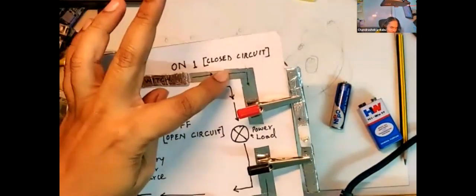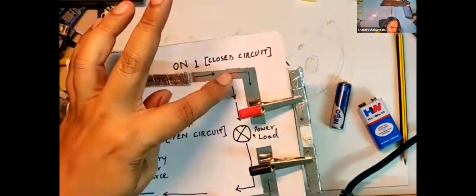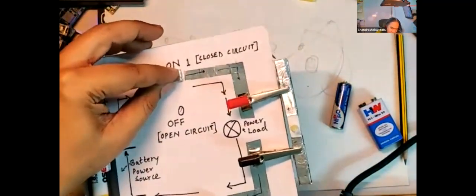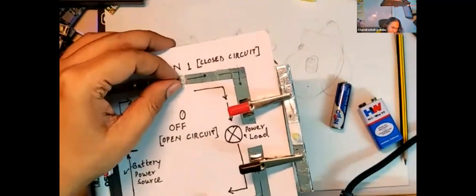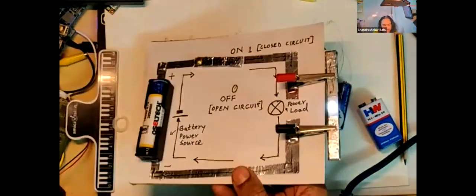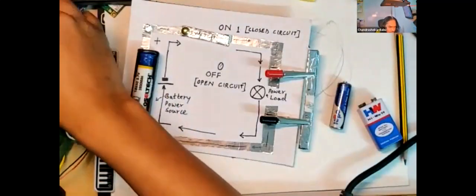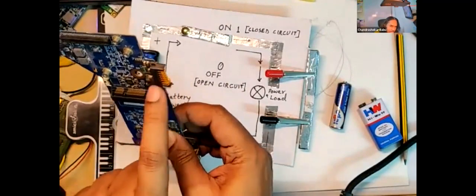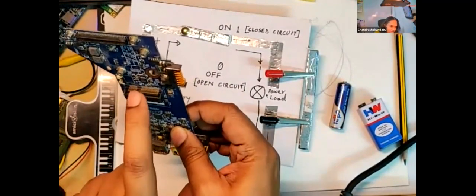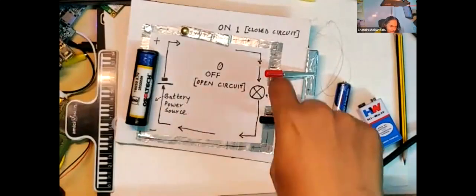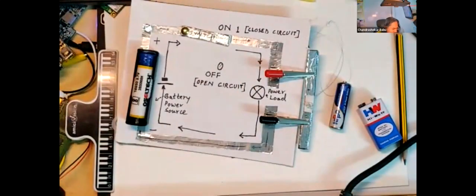So yes, many of these metals might get an oxide layer, and once they get an oxide layer, they will not conduct electricity very well. And when you have flickering lights like this, it's called a loose contact. The contact is not tight, so the electricity is not flowing all the time. To avoid that, when they make these circuits and connectors, they plate them with gold plating, so that gold does not corrode, and therefore it will not lead to loose contacts. If I had made this with gold, it would have been intact, but gold is very expensive.